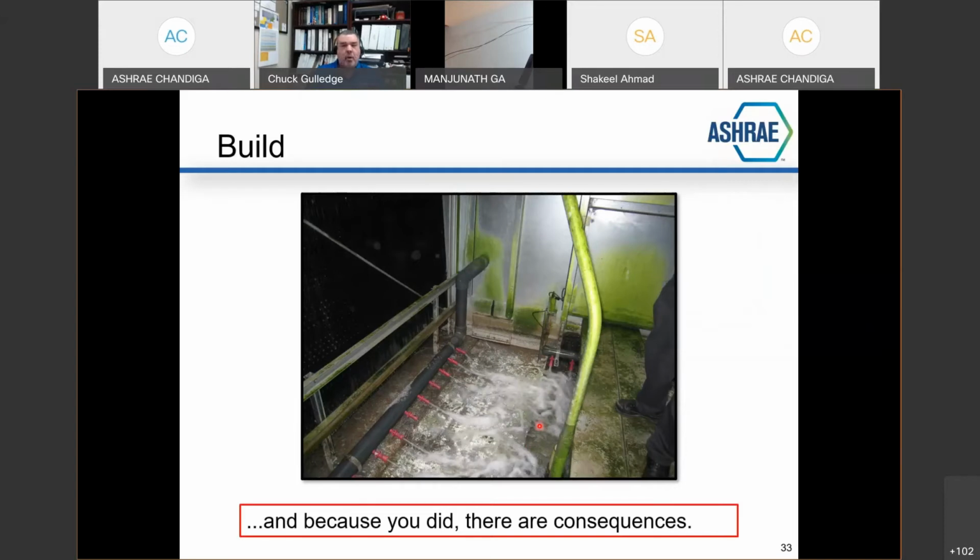They dumped all of the chemical dispersion that was taking place inside the loop of the condenser water. They were getting air into the collection. They were cavitating the pumps because there was truly now air inside the system. All of this was exposed, and the residency time of the chemical treatment was gone. And look at all the green stuff growing inside the cooling tower.